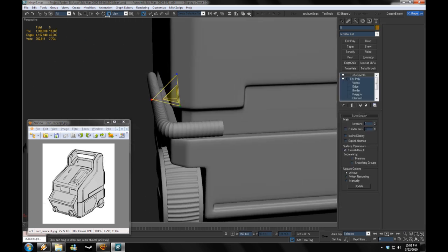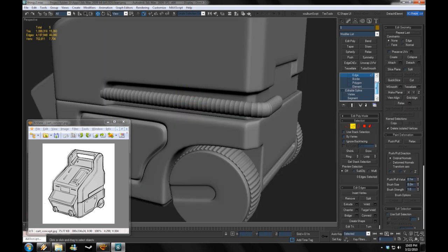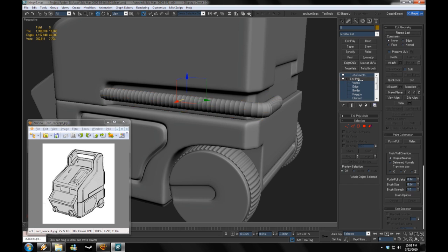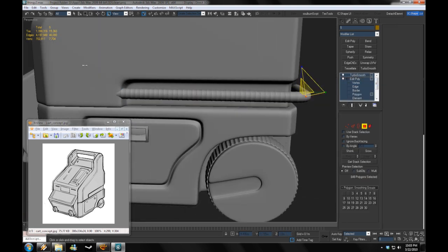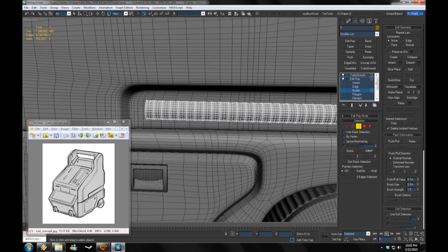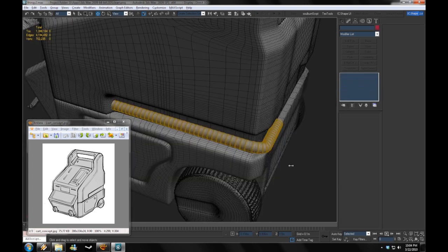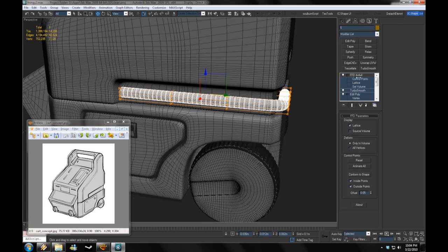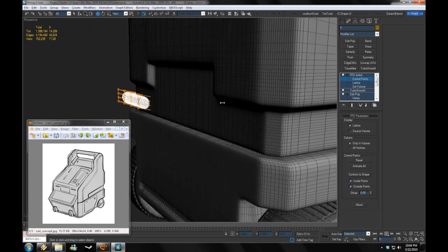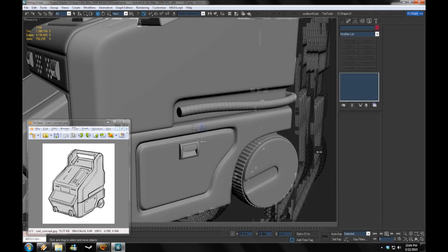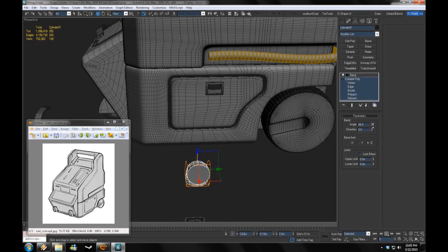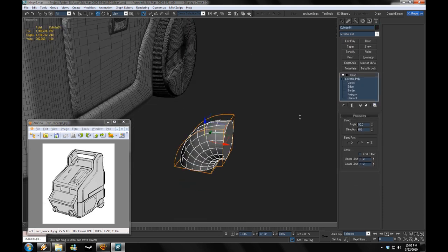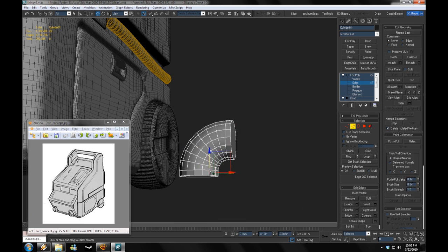And now I'm adjusting it so everything is proportionate to how it needs to be. It's not weirdly proportioned. And I'm going to play with some freeform deformers in a second here. Now the FFD deformers are a set of modifiers that will present you with a grid, and you will be able to deform your mesh here by selecting certain control points. And you can also adjust those control points as need be and select different volumes. And that's very, very useful for slightly deforming things that maybe aren't perfect, or just for adding some sort of